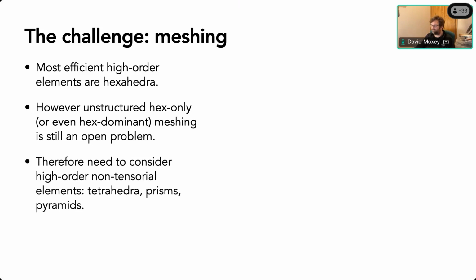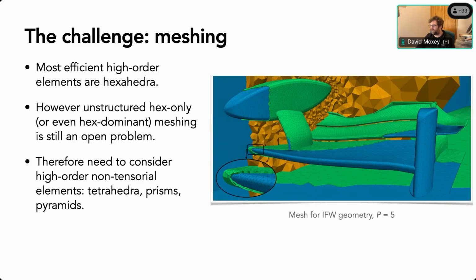So for example, if you look at the Imperial front wing, the mesh that we were running that simulation on that I showed you before, this is a prototypical example of the meshes we run very frequently, where we construct meshes from prisms in boundary layer areas, and then we use tetrahedra to fill out the rest of the space, and that allows us to deal with capturing the geometric fidelity we need for bending these elements to fit the CAD geometry underneath it.